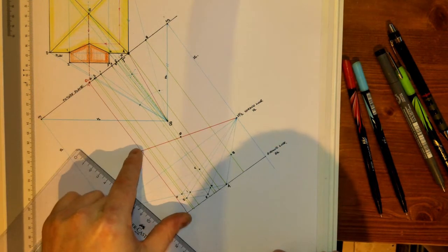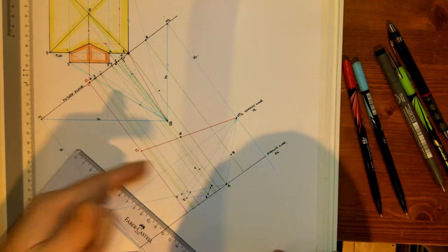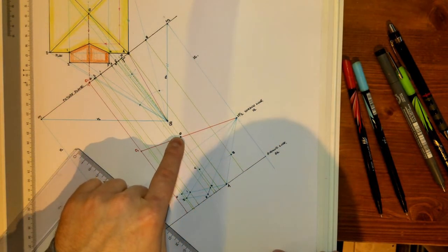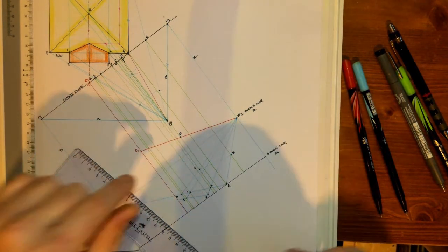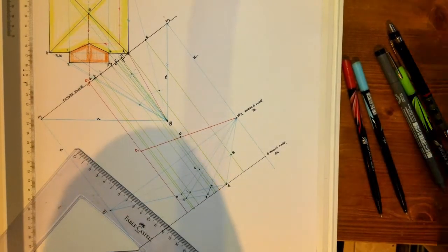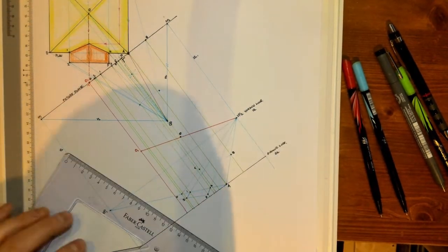We brought it down. We took the true height for O because now technically it's on the picture plane. We mark 80 millimeters up. That's the true height. Bring it back to the furthest vanishing point, or the one most relevant to the point. And where it intersects the projection line for O coming down, well, that's our point. Apologies there about the light on my visualizer. So there's point O found.